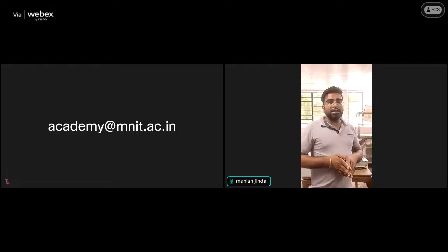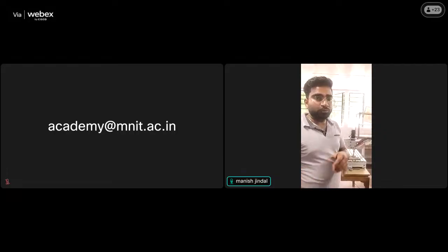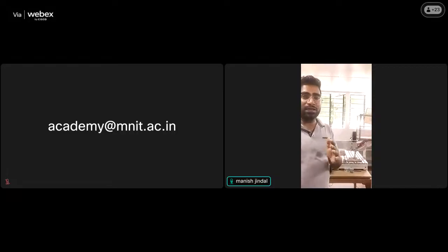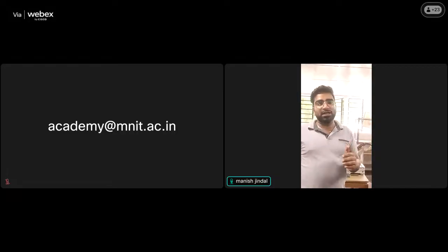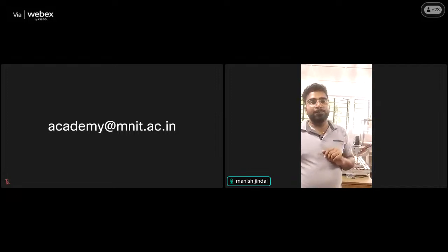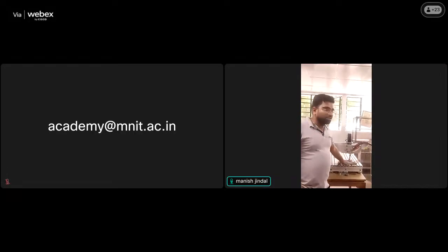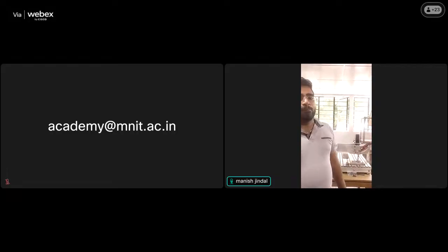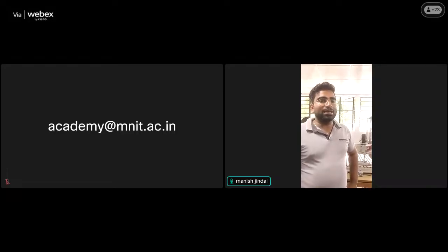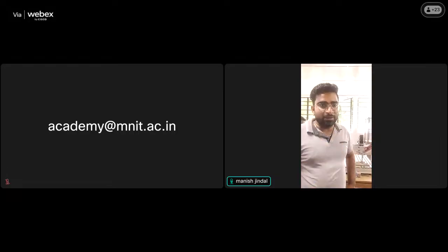steady state responses. Actually, the point is that before making any part, we will create some beads on the basis of hit and trial experiments. On the basis of that, we decide the input parameters, accordingly the design matrix. Suppose we want to make a single wall structure of SS308L material. What should be my input parameters so that I can get the best welded part, the best 3D printed part?